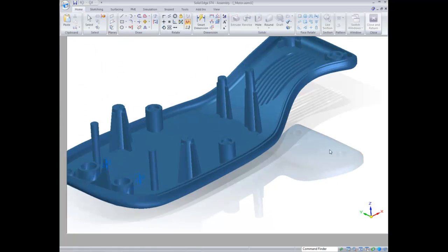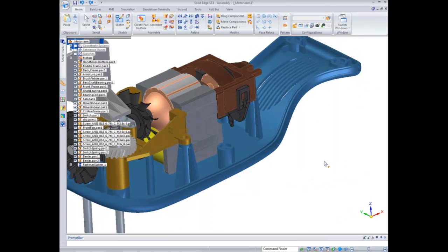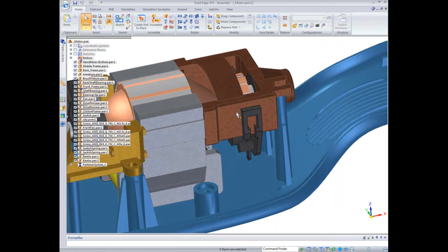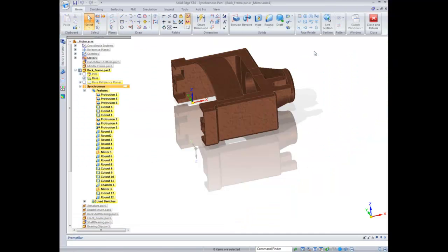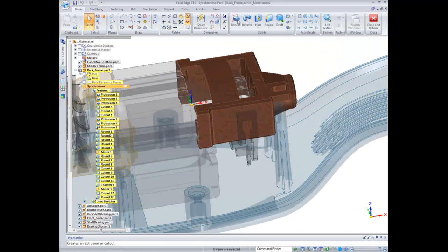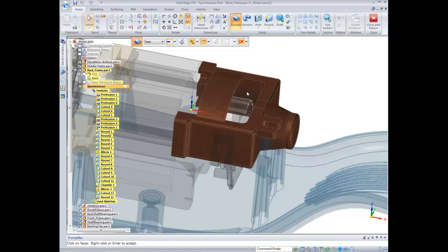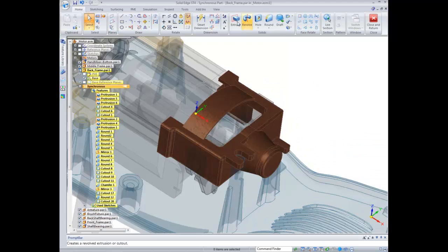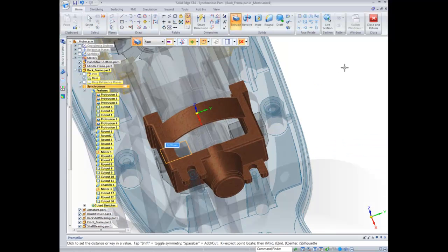We'll add another cutout to a part back here. You can see that the black piece is going right through this one, so we need to come in here and edit this and make some cutouts. So we'll turn on the background levels, use extrude, we'll grab the top face of that black part, and we want to cut, so we'll just hit spacebar and it'll allow us to cut. We'll just cut straight down from it. We'll click extrude again, do this side, and cut down through.